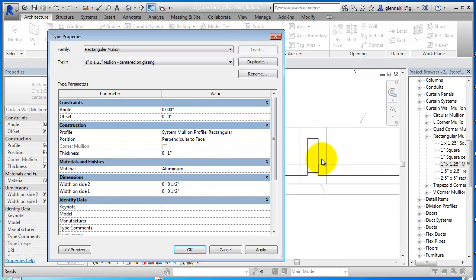So what I want to do is move the mullion, and I don't want the thickness, so I'm going to move it now, and this is positive and that direction is negative. So I'm going to come in here and say 1 inch, let's say, and I'm going to apply that. And notice it moved it 1 inch. That's a remnant of the graphics card. But it moved it 1 inch, and notice that's not enough. It needs to go some more. And actually, since I've already done this once, 1.25 should do it. And if I apply that, it's centered.